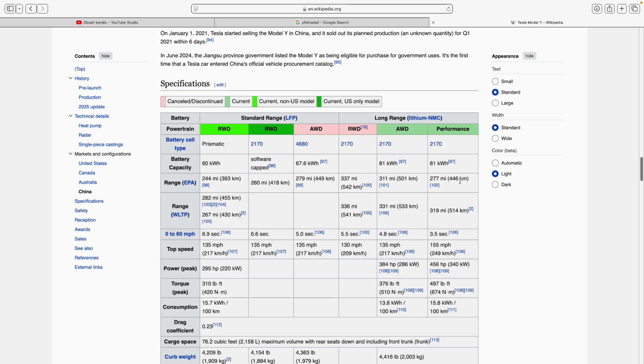So let's say that you drive 1/7 of the range per day, which should be enough for you to get to work and back or wherever you need to. And so it's just 81 divided by 7. That's a daily value you could use for the load profile in this case.